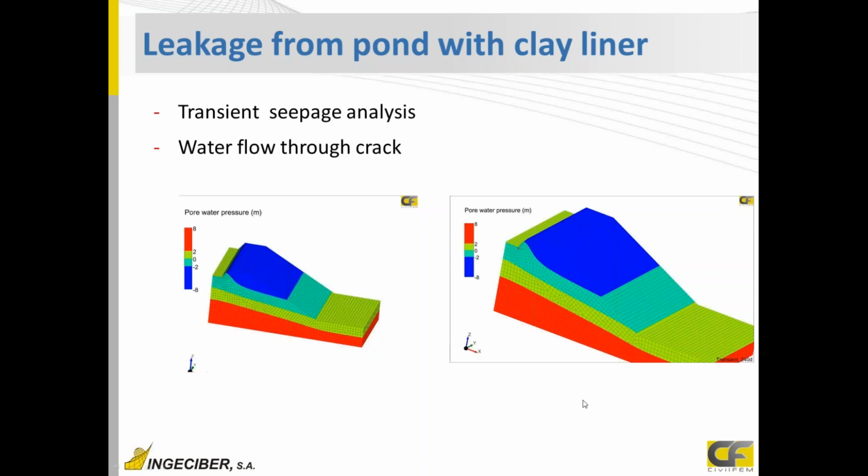impermeabilization of the model, and we solve it. We start the model with this condition, this previous pore water configuration. We start on this, and we see the seepage results through the model, how the pore water pressure is increased, the water table also is increased, and different results through the model. So as you can see, we can solve also transient seepage analysis with different model configurations and those results.